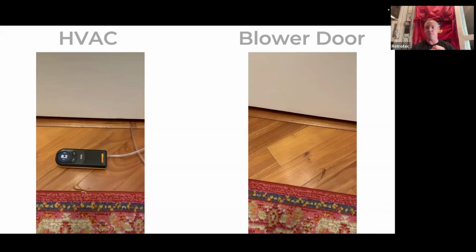So that's one of my favorite ways to use that handheld fogger: to pressurize the house and then just shut doors. Whether I'm talking about a residential building or a commercial building, for commercial tests, we do this a lot in hotels, hospitals, and schools. Lots of times you'll have rooms along an exterior wall. So just start shutting doors, get your pressure up, and see if you have fog that's being pushed out underneath. That's a way you can see if that room needs more attention paid to it to see where those leaks are to the outside. So it's just a quick and easy way to check if there's a problem or not.